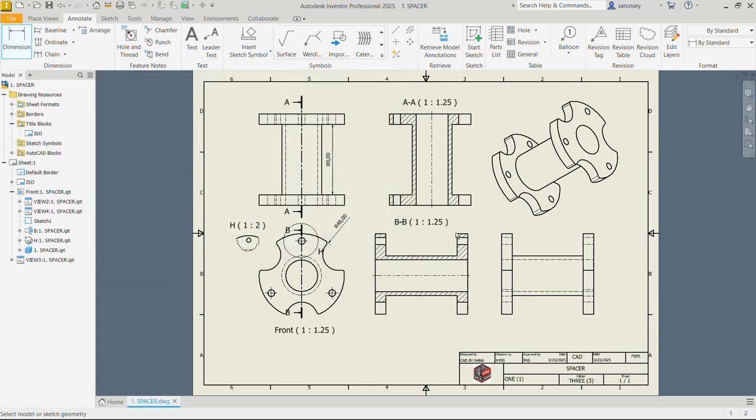You can keep on doing this for all the lines and circles you have, but I don't usually like doing this, and so I'll take some few steps back. Control Z. Let's do Control Z and another one. Now we would use the baseline command. Here you will pick the baseline for which you want to apply the dimension. Let's say this one, we pick another line, also this and that. Once you are done picking the lines, you right click and continue, and you see the dimensions that are shown. You can click wherever you want to place it.